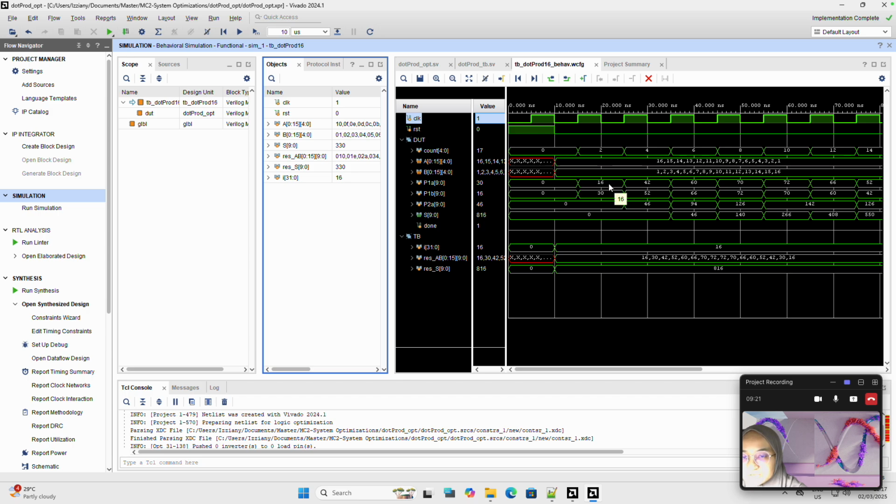If you remember from the code just now, P1A and P1B multiply two data elements A and B together. P1A processes the first count and P1B processes the next count. It does this process in parallel, and then passes the data to be summed together in register P2A.